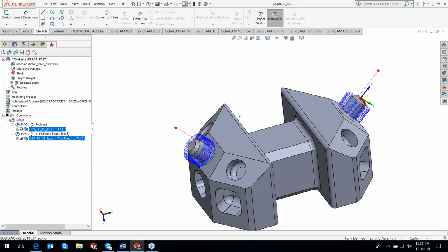What we are now working on is that the same interface can be used for mirroring HSM toolpaths, and even there we will keep the machining direction the same. We'll keep climb as climb, conventional as conventional. So this is a pretty unique thing that we introduced now in 2018. It should be on your versions pretty soon.